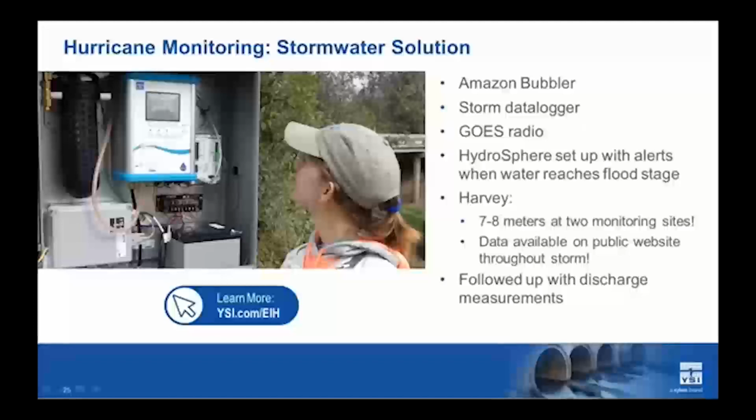Now, during Harvey, the level in those creeks rose 7 to 8 meters at two of the monitoring sites that we looked at. The data are available on that, but 7 to 8 meters of change. They were able to use those stage measurements with those discharge relationships they had previously built to better understand potential pollution that went through those creeks during that stormwater event.